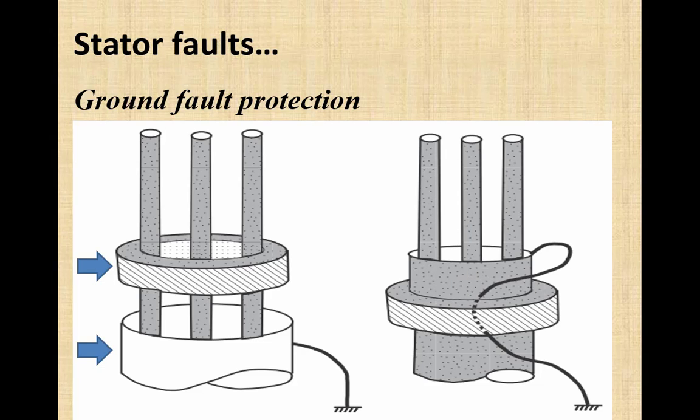If it is not possible to keep the sheath out of the core of this flux summing CT, then we will have to cancel out that current by threading this grounding conductor back through the core, so that it will cancel out the current carried by this core. So here actually this armor around the cable was carrying a current in this direction, flowing into this neutral circuit, and this conductor has been passed back through the core of this toroidal CT to cancel out this total current.